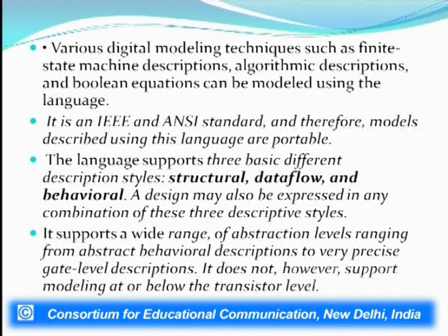The structural and behavioral I have already mentioned. Data flow simply defines the data between the signals, that is from input to the output, or intermediate nodes if any. We will discuss it in detail as I move forward towards these styles. And there is a mixed style modeling also supported by VHDL, wherein all three of these techniques or any two of these can be integrated to develop one particular hardware description.